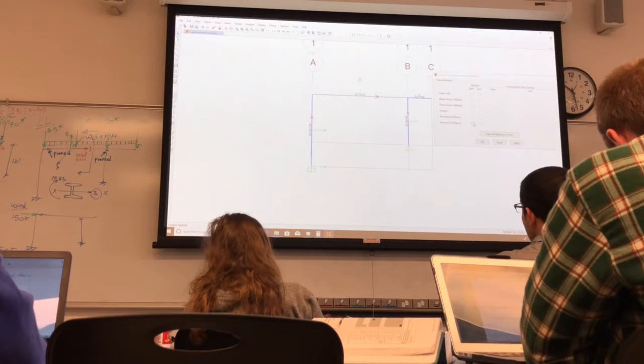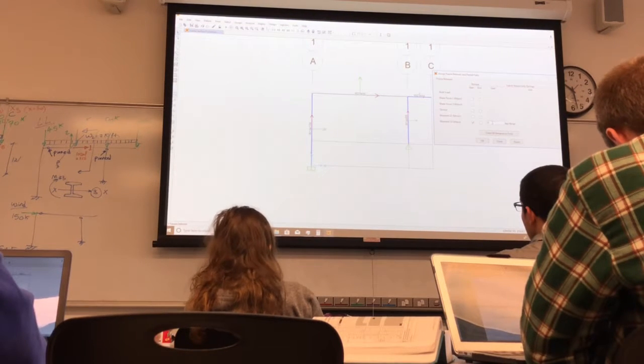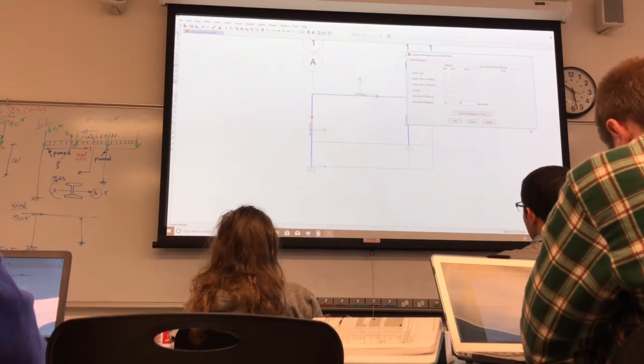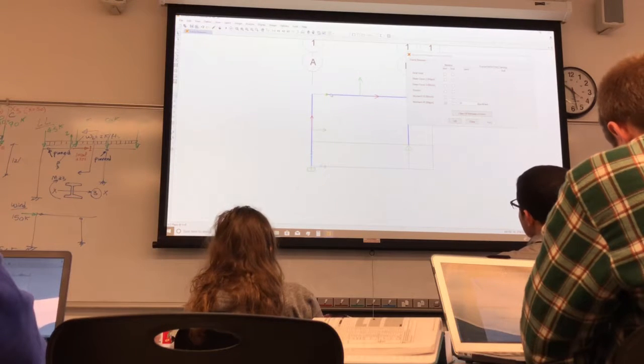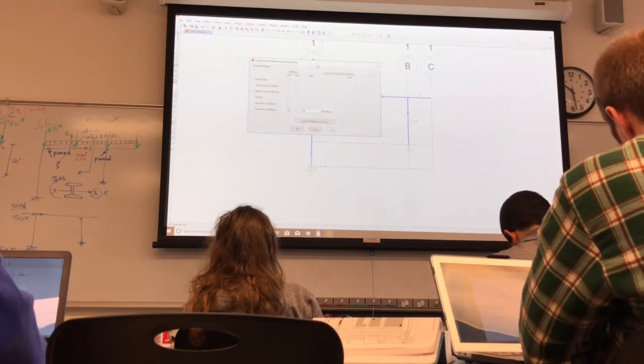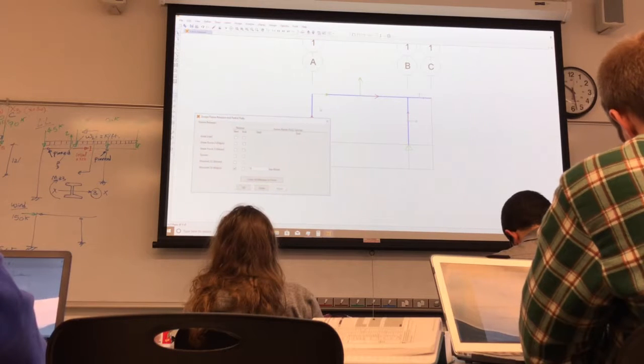So I just select here start, and it's pinned. I put a number only if it's semi-rigid, if it gets some stiffness, but it doesn't because it's pinned. So I keep it as default, and I click apply. You'll see it draws a pin here at the start node. So it's a start one. And so that takes care of this pin.